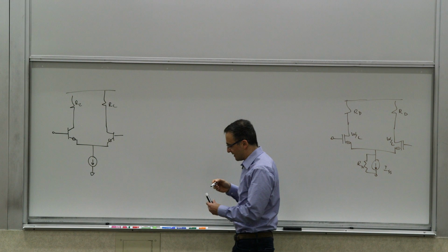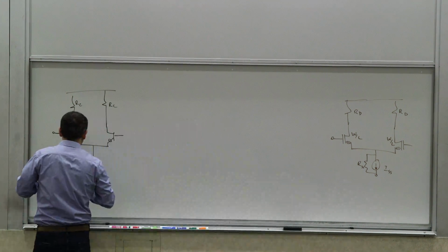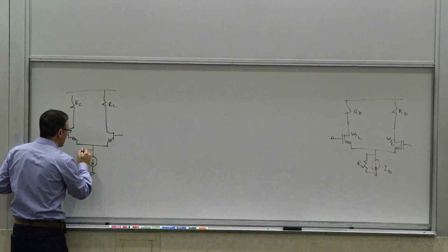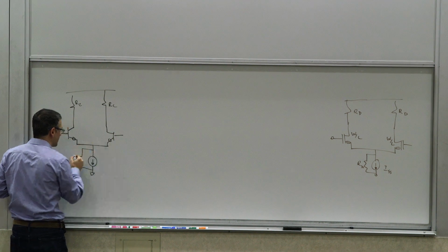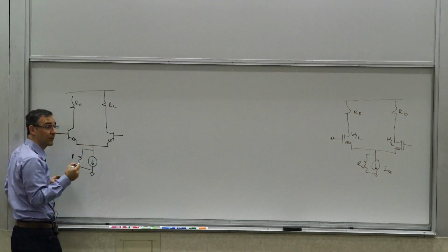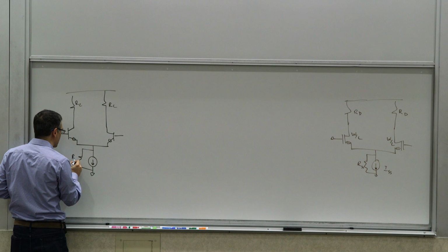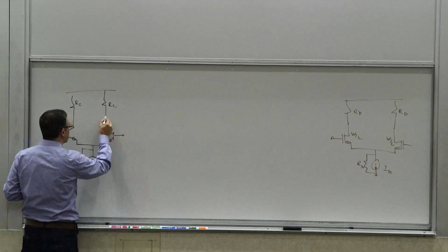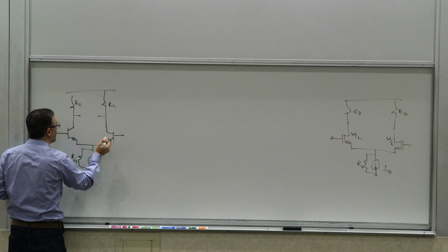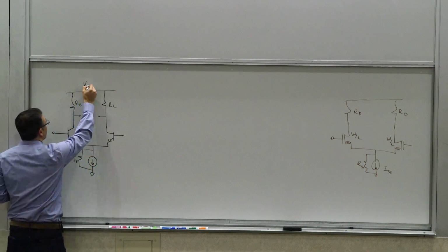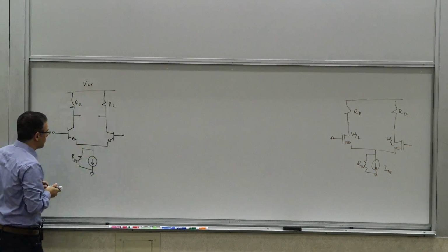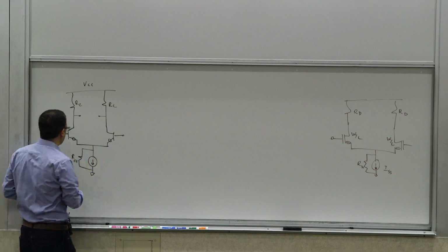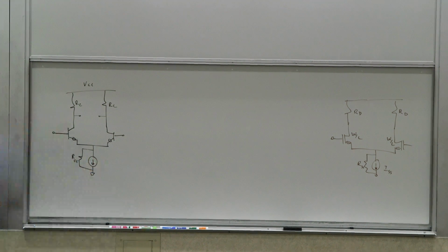We talked about that if you want this to operate properly, you want them to be matching well, so the two transistors need to be matched. We talked about different ways of making them match well, for example common centroid structures that allow you to make this differential pair match better. There are different variations that give different levels of matching and accuracy. But anyway, this was the essential stage.